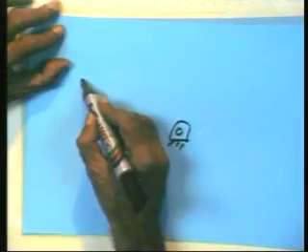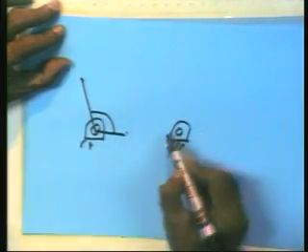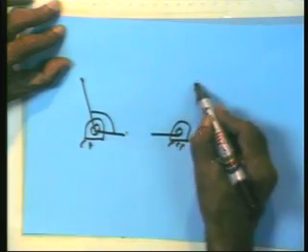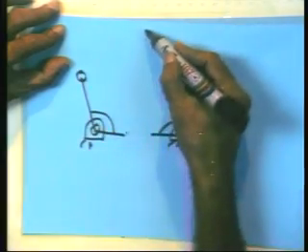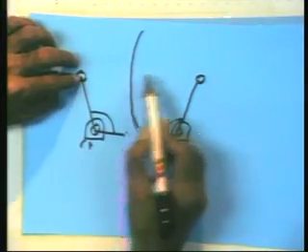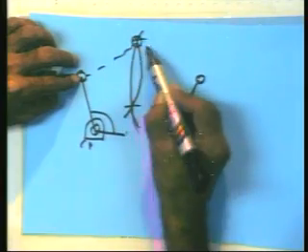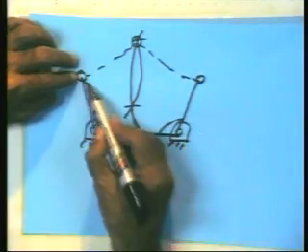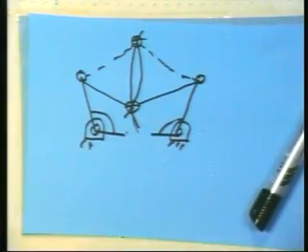So I am given the base, I have drawn the base. I have drawn the two cranks. One is here. This angle is given to me. This particular angle is given. So I draw the other crank because the other angle is also given to me. Then I put my compass here on this revolute pair. Draw a circle like this. Then I put my compass here, take that corresponding link length, and draw another circle. So I get two intersections. So I can assemble this five-bar either this way or that way. I call it two modes of assembly.